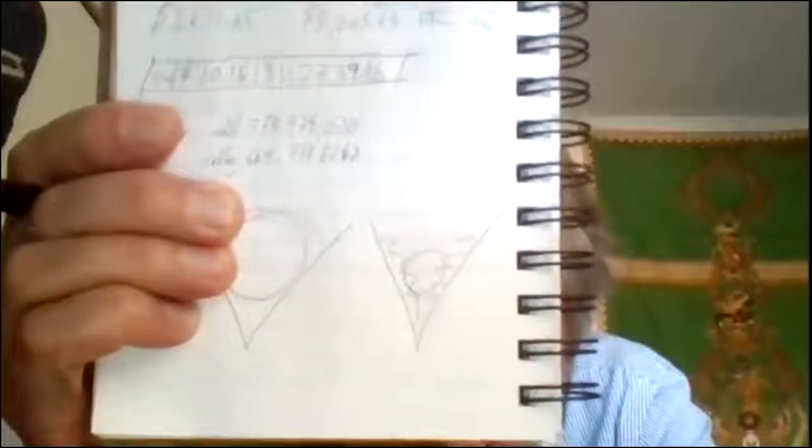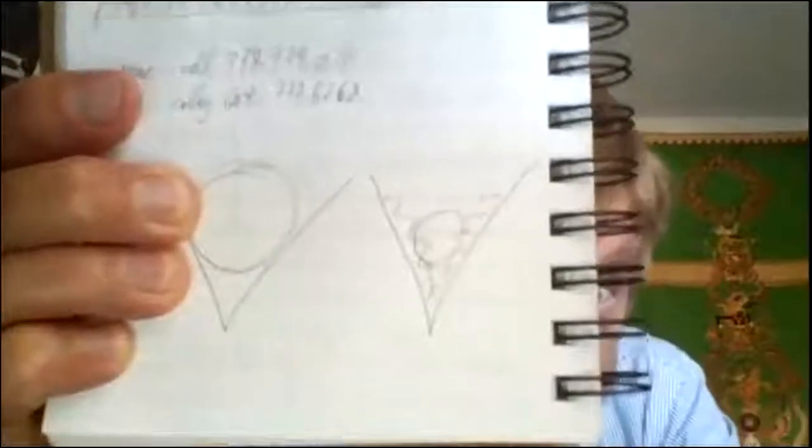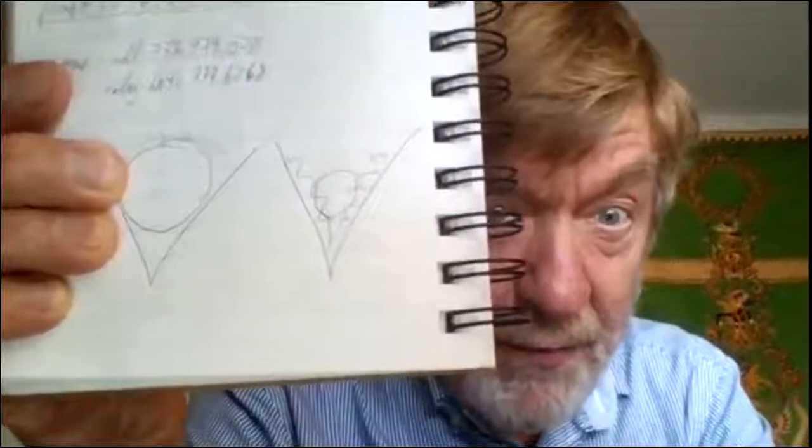And so the needle is dragging along those little bumps, okay? Now, what happens is when they made the record, someone was singing into a mic, and the mic changed the sound into electricity, and they had a soft wax platter, and the electricity made little wiggles because it was analogous to the sound waves, and it created analogous little wiggles inside the grooves, and those were let to harden.